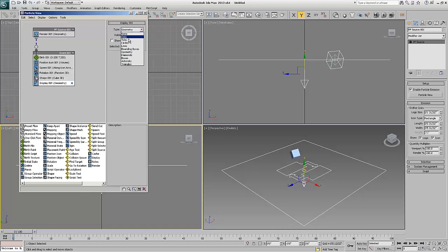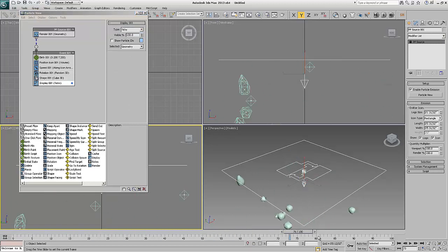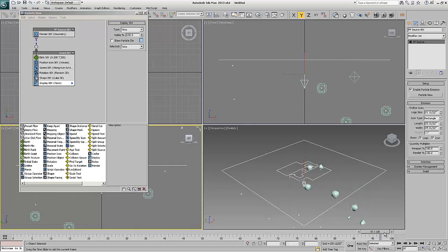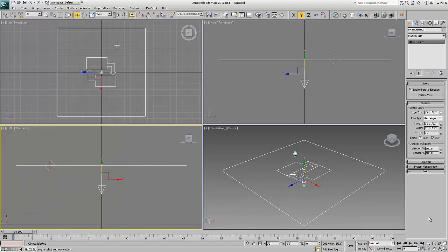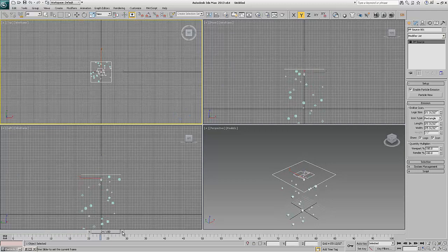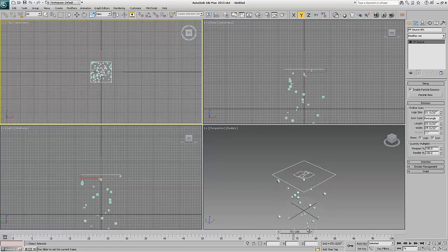Alright, that was wrong. Let's turn that back to ticks, so we don't want to see the cubes. The ticks show us an approximation of where the cubes are, and then we get to see the blobby mesh. Now, at this point, you can tell this does not look like liquid metal, obviously. The key to using particle systems in blobby mesh is to keep the particles close together, and that way they form the kind of water or liquid look.